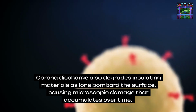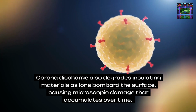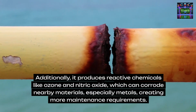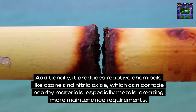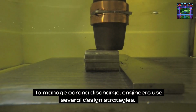Corona discharge also degrades insulating materials as ions bombard the surface, causing microscopic damage that accumulates over time. Additionally, it produces reactive chemicals like ozone and nitric oxide, which can corrode nearby materials, especially metals, creating more maintenance requirements.